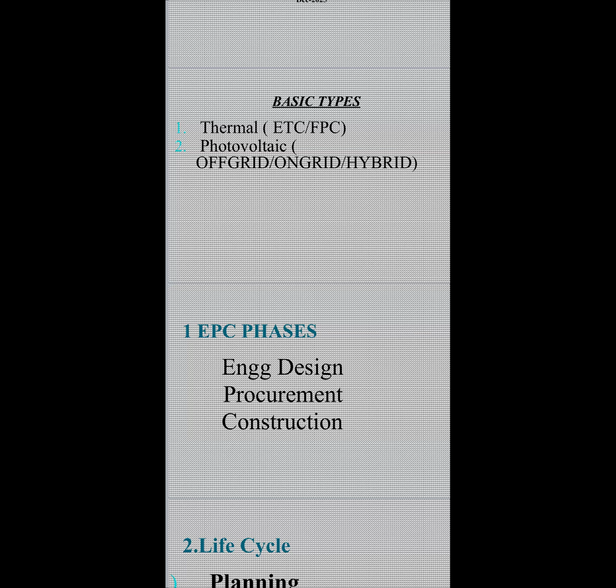In this, there are 3 types of power plants. One is off-grid, the second one is on-grid, and the third one is hybrid. Off-grid, as the name says, it does not export any energy to the grid. It is, in simple words, just a home UPS connected with the solar modules. It's as simple as that. You cannot export any energy to the grid. Whatever energy is generated, you have to just save it in the batteries or consume.